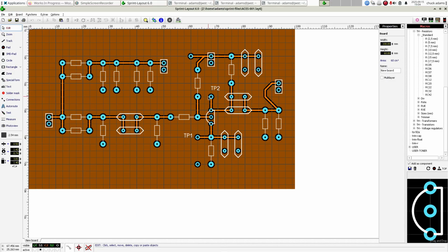If I measure this one and subtract this one, that'll give me my collector to emitter voltage. And then we're going to go back to some data sheets and see with different measurements how the transition frequency varies due to bias and whatever on the transistor.